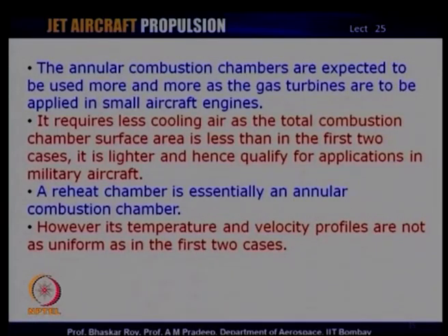The temperature and velocity profiles are not as uniform as in the can type or the cannular type, because you do not have that kind of control as with the flame tubes of the can type. So, the annular combustion chamber may not deliver a very uniform temperature and velocity profile onto the turbines.